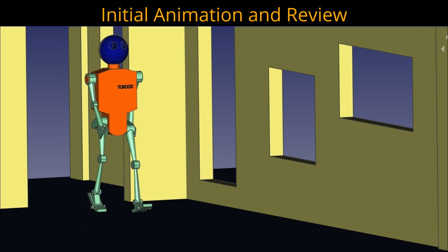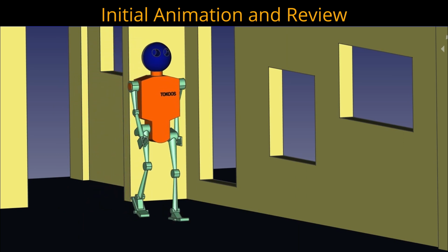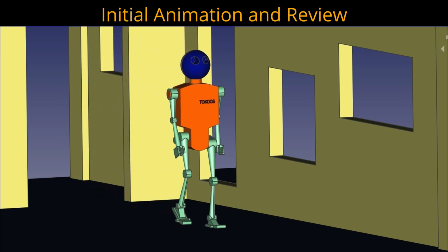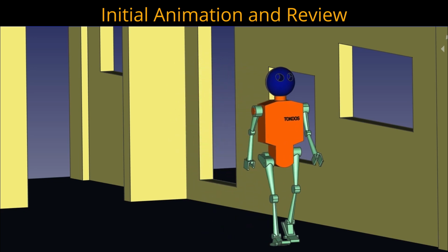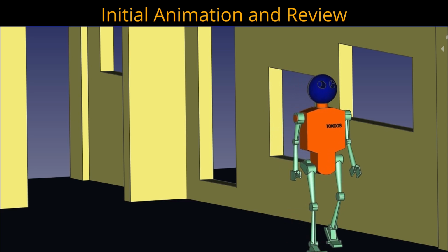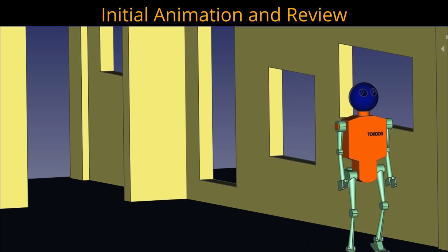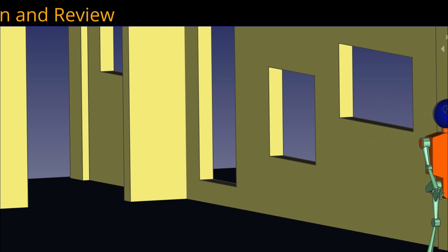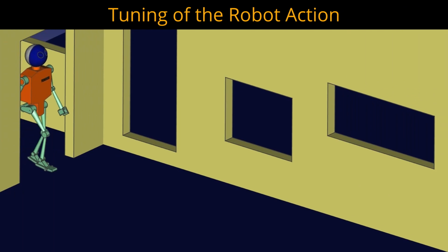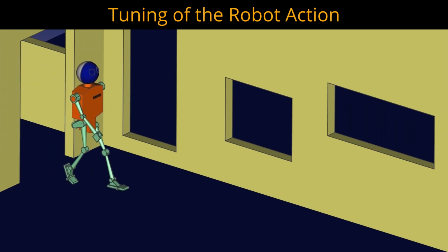Finally, trial animation was done on the assembly workbench in FreeCAD, with the reference value as the primary variable, and reviewed. Reviewing the initial animation, the tuning of the robot action could be done thanks to using this parametric 3D modeling software. I modified initial data and graphs and accordingly modified those equations for each constraint.